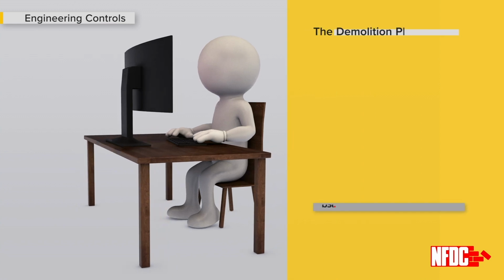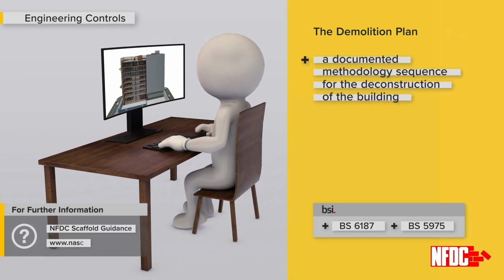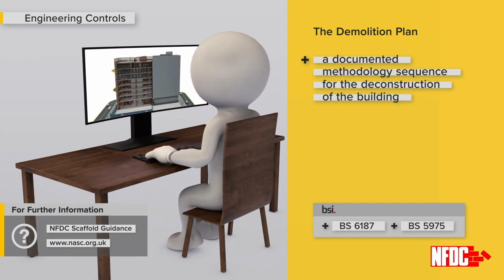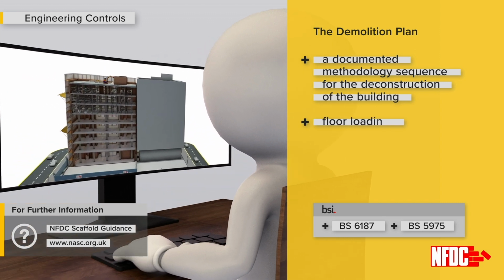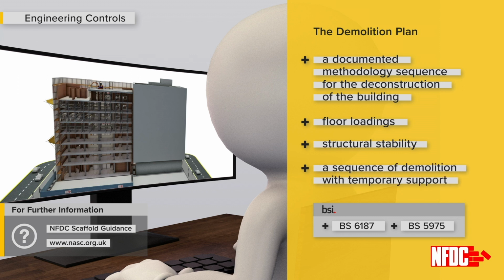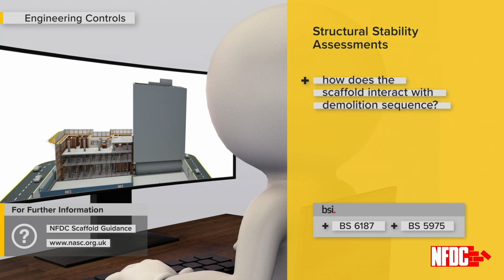A key part of the process of demolition is planning using a documented methodology sequence for the deconstruction of the building. The demolition plan must be designed according to the structural constraints. These include floor loadings, structural stability, and a sequence of demolition with additional temporary support as deemed necessary. Structural stability assessments must be carried out and take into account how the scaffold interacts with the demolition sequence, all in accordance with British standards.